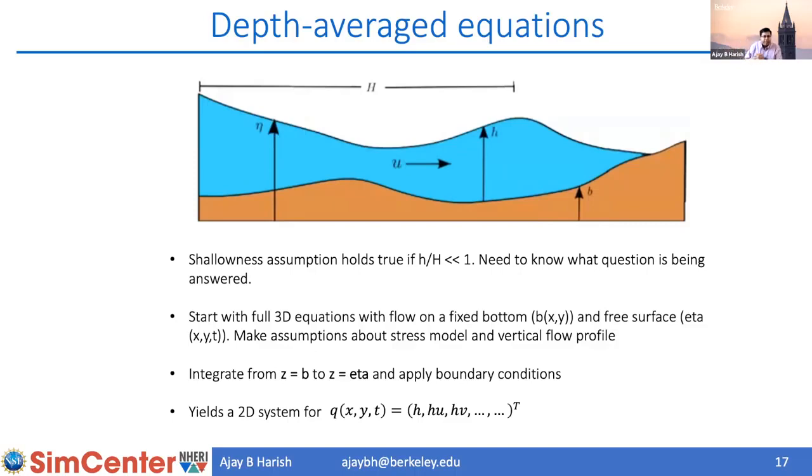Then we probably want to use nonlinear solvers, the nonlinear shallow water equations, to ensure that we are correctly capturing these phenomena. That's where we bring in a full 3D CFD simulation once the wave comes near the coast, in order to capture the entire event.